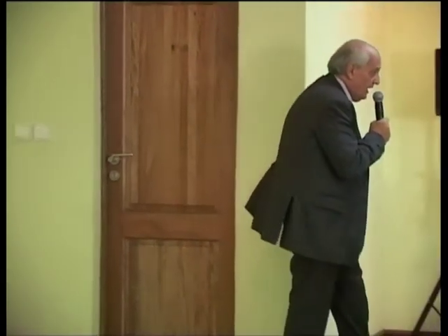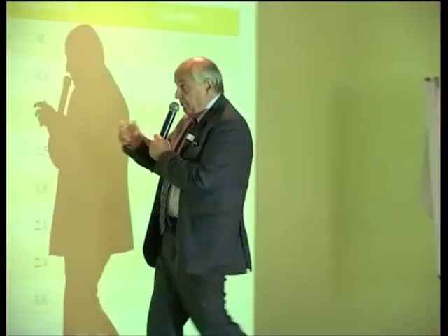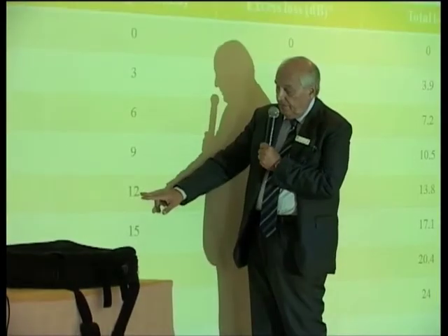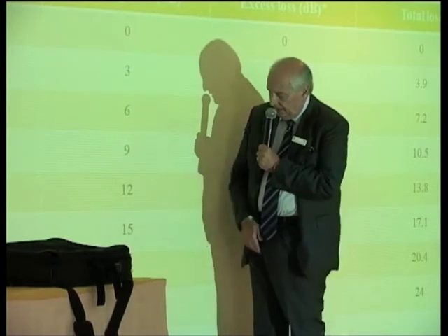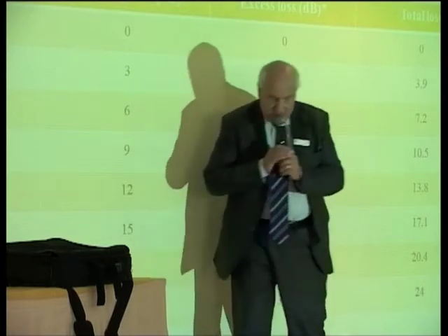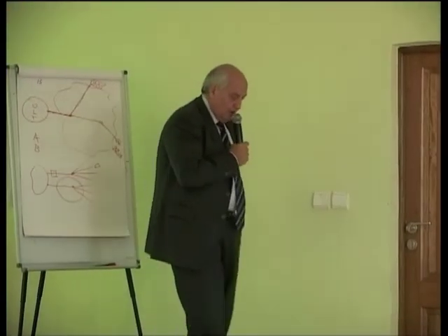The splitting loss, the theoretical splitting loss, means I am dividing the pulses between the users, so any time I divide by 2, I introduce a loss of 3 dB. If the splitter is 1-to-2, I introduce a loss of 3 dB. 1-to-16 is 2 to the power 4, so I have to take the exponent and multiply it by 3, which gives 12. And this is the maximum loss in the splitter. This is the theoretical loss. We cannot have a loss which is less than this.